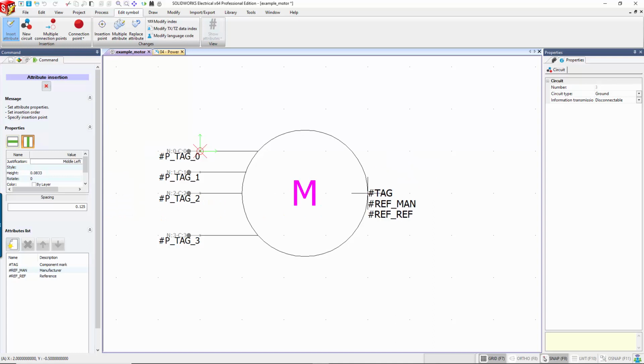And you can see for an example that it's left justified like I told it to. You can change the text height. So if I want to say all of this stuff is 1/8 of an inch high, I can do that. I can make the spacing a little bit further. Maybe I want everything 1/4 inch apart. Yeah, that looks cool.